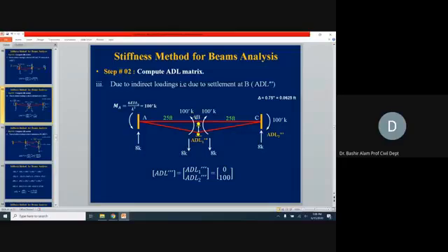This is why I always urge you to sit with the calculator so that you get practice also. Sometimes you know how we should apply the equation and what numbers we will be multiplying, but when you actually do it on the calculator, you make mistakes. Now you saw the example also. So this 25, this 100 and 100, luckily the 25 was on the right hand side, so that moment is also calculated. At the far end, their signs are going to shift in the same direction, for the left span and for the right span.